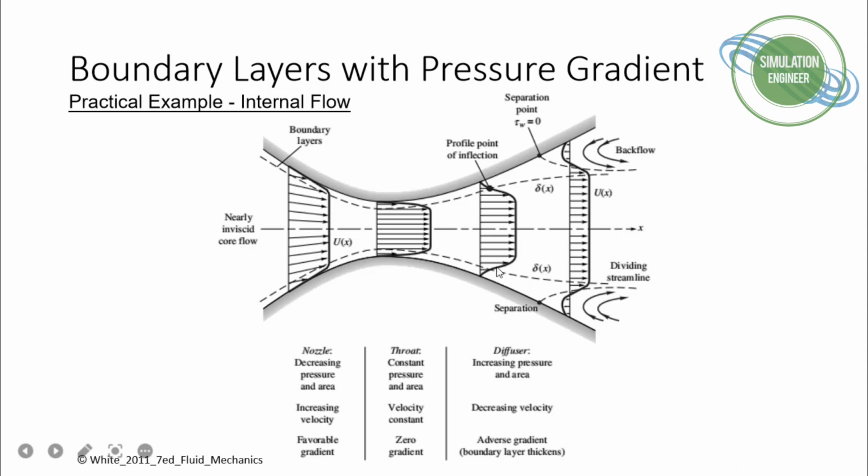So this is the point of inflection, and this dashed line is showing your boundary layer thickness. So if you really see now, the boundary layer becomes thicker, it's an indication that your pressure is now dominating the flow field, meaning that there is a decrease in your velocity, and then the adverse pressure gradient takes place. So we will be getting zero wall shear stress here. At this point where wall shear stress is zero at the wall, your separation point takes place. You go further downwards, the flow is totally separated. It's a fully separated flow region, and the decrease in velocity, this is your flow reversal. So you can see the division of the streamlines at this point.